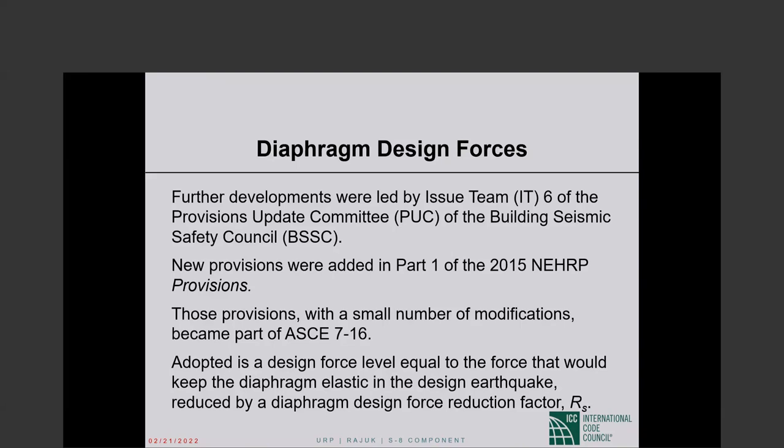Okay, and if it is high seismic, you cannot have flat plates as part of the resisting system. I told you. So you will not have a slab sitting on columns. Flat plate columns will not be part of the resisting system. So you will never have a situation where your slab will not sit on a beam or a shear wall. Yeah, that's a good answer.